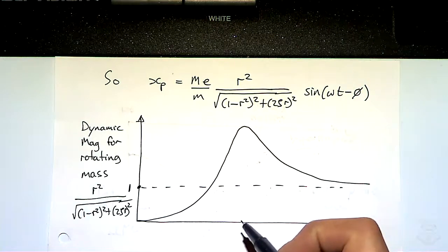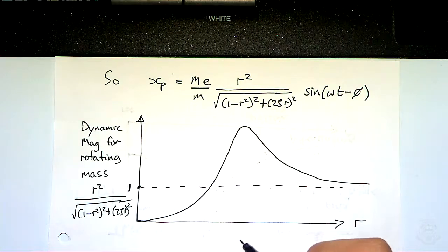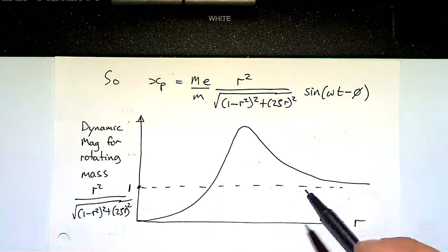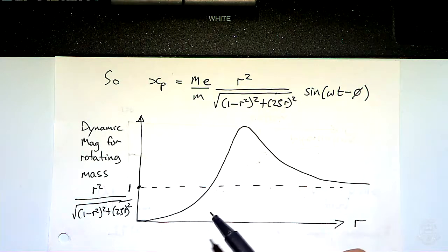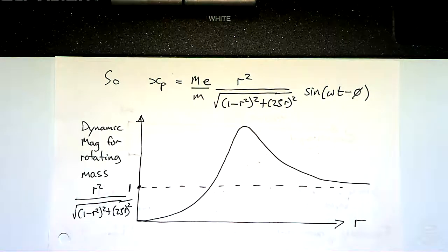This is a little bit similar to the inertance function that we looked at last time. If you remember the frequency response function where we had acceleration divided by force, it looks a little bit like this, in the sense that it went asymptotic towards 0 on this side, and it went to 1 over m on the other side. What's interesting is that you have to be cautious, because it's easy to get this mixed up with that type of FRF. It's also easy to identify if you haven't got an inertance, if you've got a displacement-based problem.